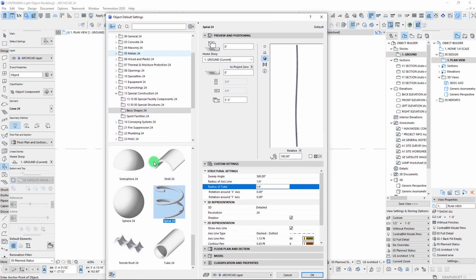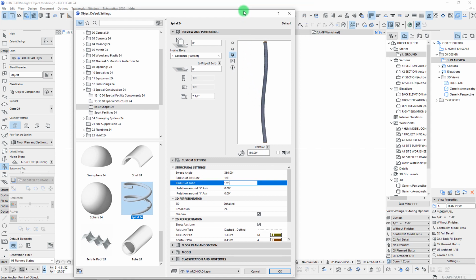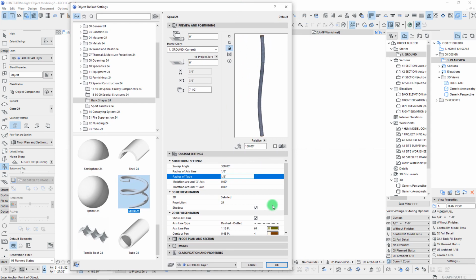This segment that we are trying to build is right at 8 inches, the gap between our base and our cap on the top. I'm going to set this to be about like 7.5 inches. And so you can see as we do this here how we're already starting to get a little bit of a spiral looking shape going. I think we're too thick right now. So let's go to 1/8 of an inch. And so let's just give that a shot and see how this creates our overall geometry.